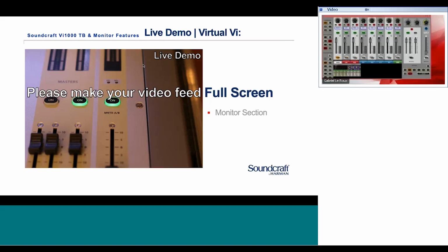When auto cancel is on, we can select our first channel, then add more channels into that specific solo, and then push any select button to clear it, which helps especially on the bigger consoles when you're standing in front of bank one and you're quite far away. It's quite nice to be able to do that.